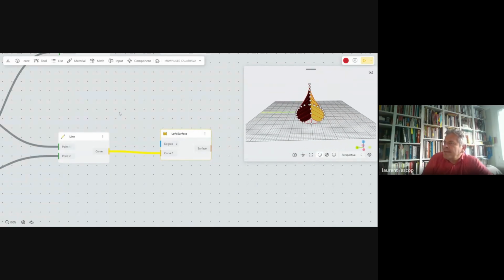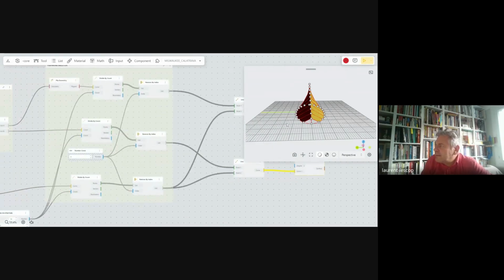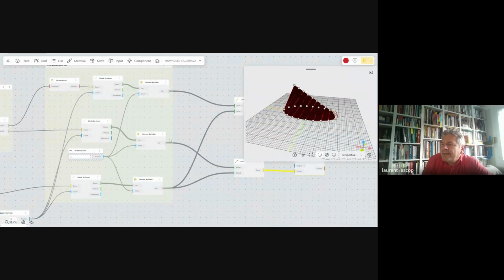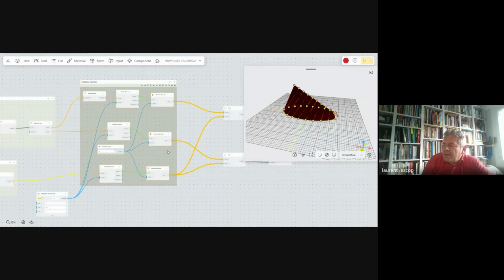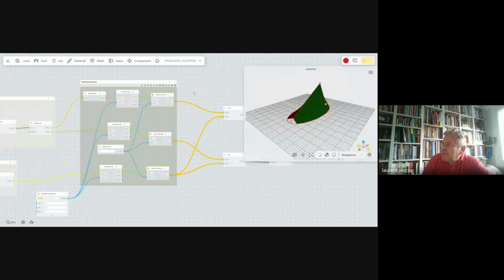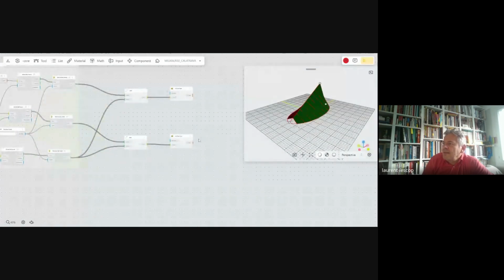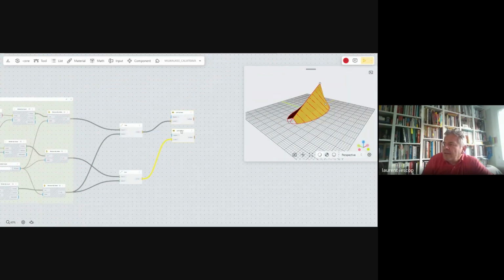We will have to hide some objects here because we've got a lot of points, and it makes things complicated. What we can do is select, for instance, a group, left click, and choose hide. Okay, this is good enough for me to carry on. So this is going to be the walls. Let's call it the walls. Here we'll make a group.